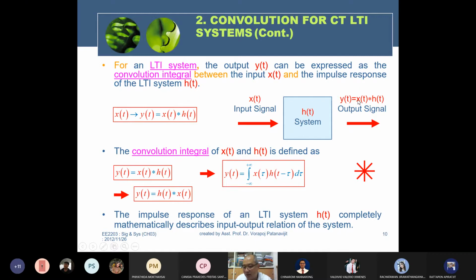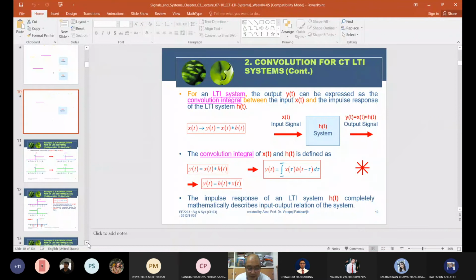You know how to determine the convolution. You fix one of them, process the other one, and change every t to τ. Then you find how many intersection patterns there are: 3, 4, or 5. In the previous example, we gave you 6 intersection patterns. You integrate each intersection pattern following that step.